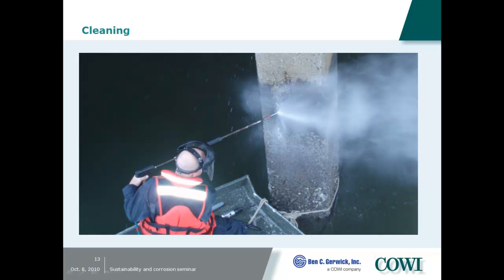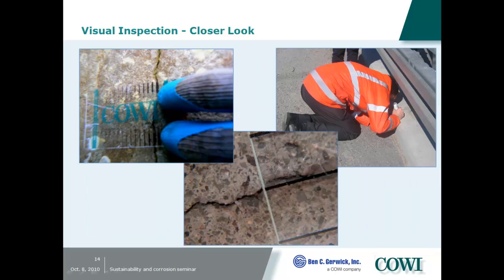You need also, in some cases, to clean your structure to know what you're looking at. Maybe there are some cracks that are not visible. That goes in particular also when you talk about below water. Below water you always have to clean your structures. You can look in more depth at what your crack width is, and you all got one of those. It has also US units on it. That's pretty good. Yes, it is actually quite good.